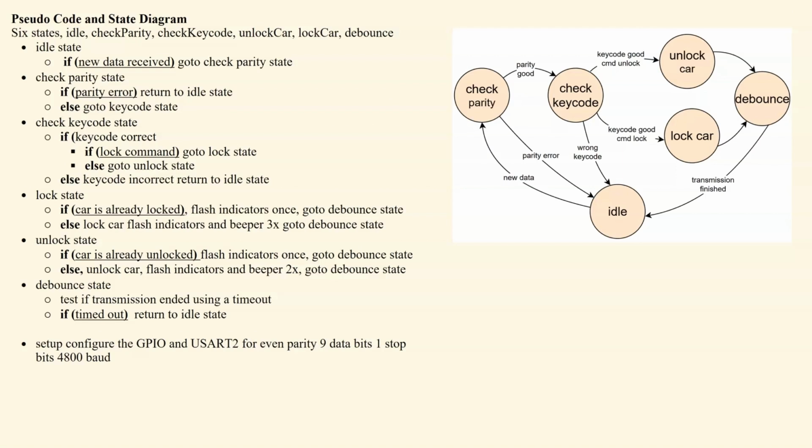I have written the pseudocode and state diagram here. Now once again, this does take a bit of time to try and work out the best plan. So before you write any code, you should clearly have your state diagram written and your pseudocode. From there you can just straight away write your code without having to think. The thinking occurs here. So basically we have an idle state.